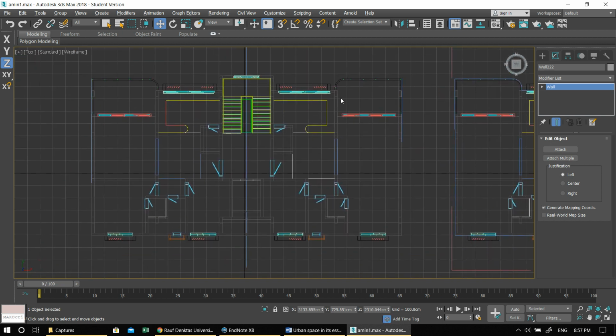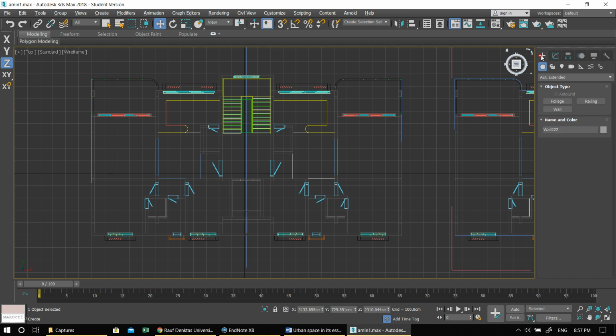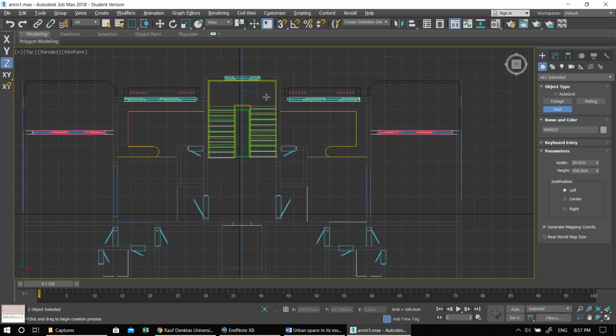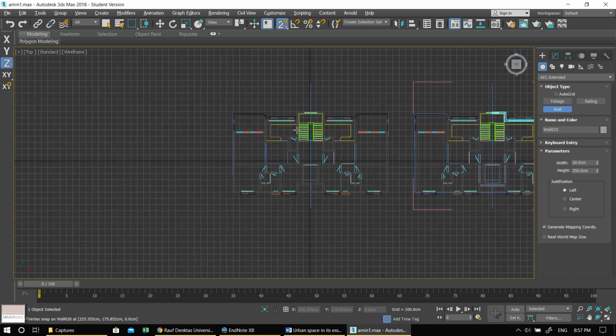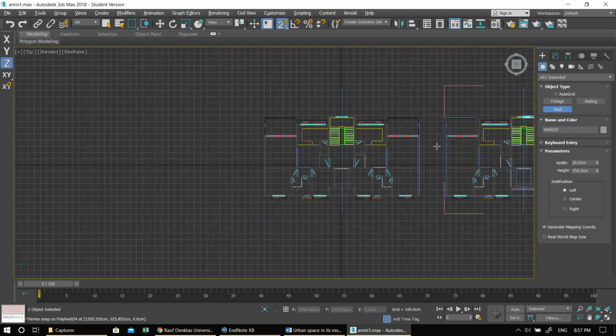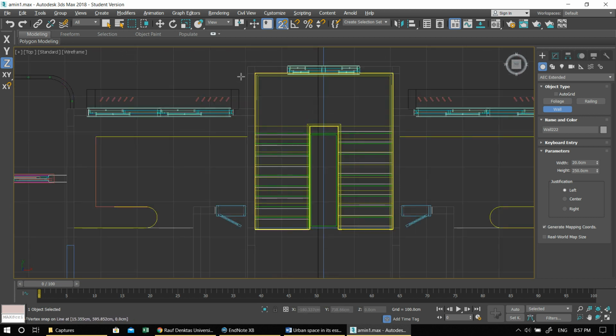Again, it's a wall. It's not something really fancy. So just a wall. First, I'll do the part for the staircase. Again, architecture, wall 20. For the roof 30 is too much. Let's say go 250. Snap on 2.5. I don't want it to go crazy. I can even do it in my working plan, because I don't know where it goes. So I'll start actually doing it here.